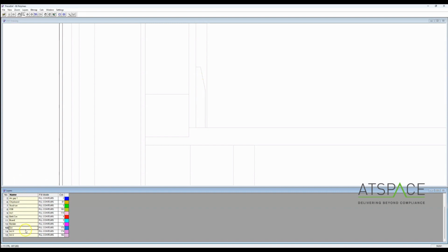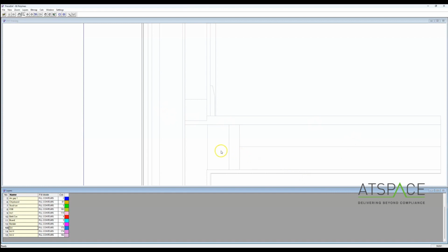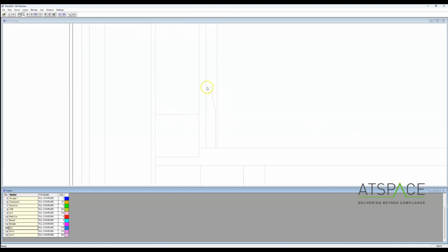We organize that by selecting the layers down here that we want to organize, and then you've got two arrows up here. If you move it up, it has a lower priority. If you move it down, it has a higher priority. I would recommend putting the work in during the CAD stage, so there's not too much stuff overlapping. So there's not too much priority for me to set, but just to show an example, I'm going to move all the boundary conditions to the lowest priority, as that's quite a common thing.